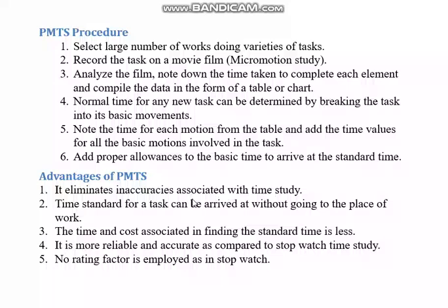That is, very small duration activities PMTS is undertaking. But anyway, as an advantage they are saying it is eliminating the inaccuracies that are there in the time study. Time standard for a task can be arrived at without going to the place of work.